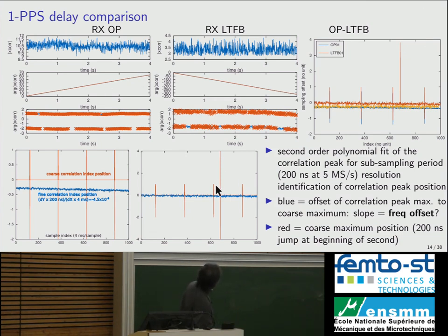So this gives you, again, the same information, except that this time, this is not ranging information. This is a time comparison between Paris Observatory and Besançon. So these are two received signals. This was transmitted by Paris. This was sent and received by Besançon. And here you see that the time offset is, of course, less than 4 milliseconds. The two observatories are aligned.